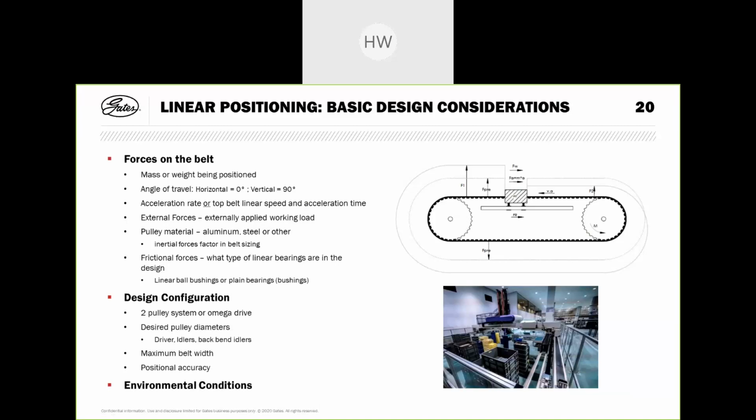In standard applications with small pulleys and aluminum pulley material, that's usually not that big of a factor, but when it comes to big pulleys and steel material, then it's worth respecting the inertia here. And then, of course, we also have some frictional forces, mostly with linear bearings. That is also minimal, but at least it's worth double checking.